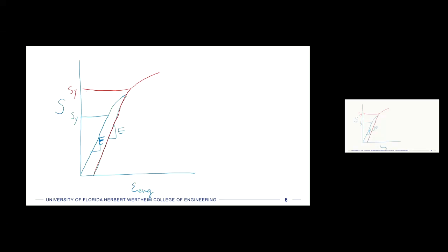And it always takes place in this stable plastic regime. And so when we unload it, we get back the elastic strain that we put in, but we don't get back the plastic strain. So I'm going to draw another piece on here along the x-axis. And if I said we get back, when we release it after the first loading, we don't get back our plastic strain.